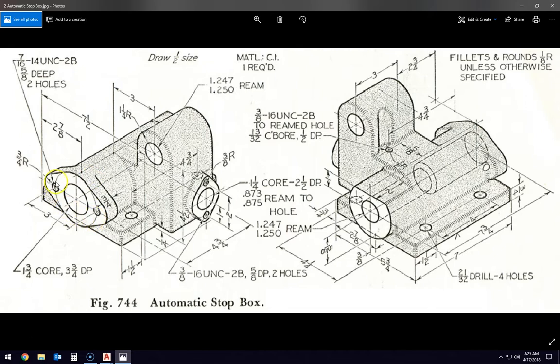So this flange that's sticking out has 2 holes that are 3 inches apart, and because that curve comes around down through here, and if we could zoom in close enough we would see a little crosshairs, that means that the outside edge of this circle part is 3 inches apart, and that's the center of those holes that go through here as well. So to me, that tells me that this cylinder that goes the whole way through here is going to be 3 inches in diameter.